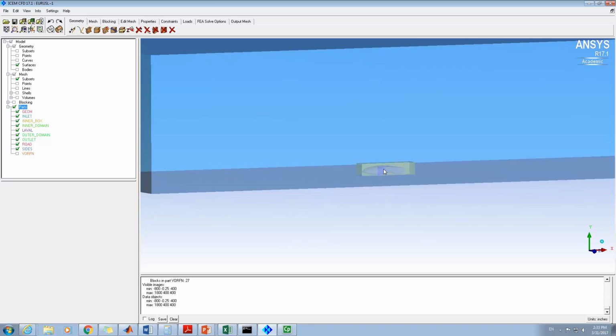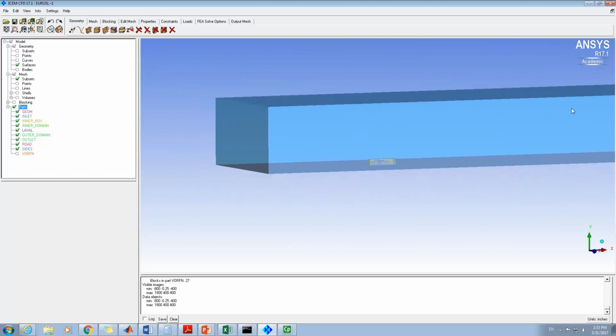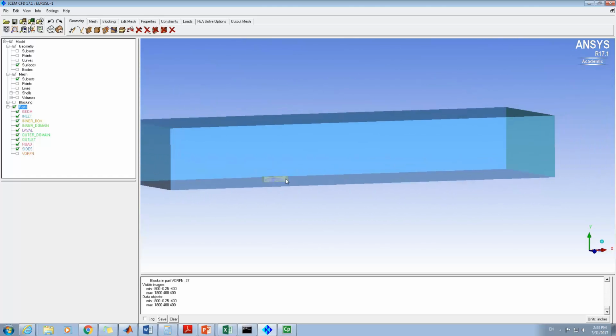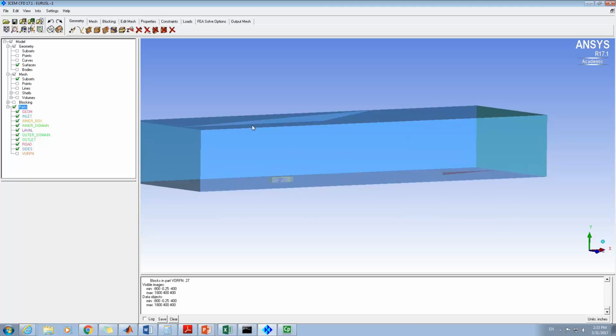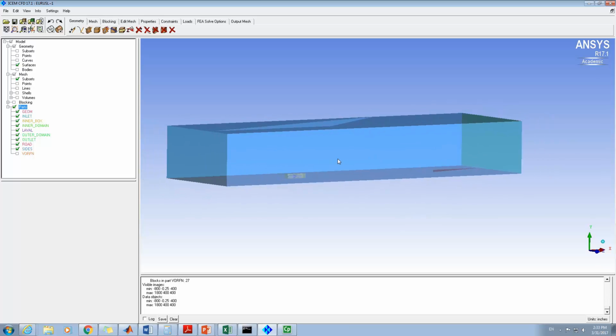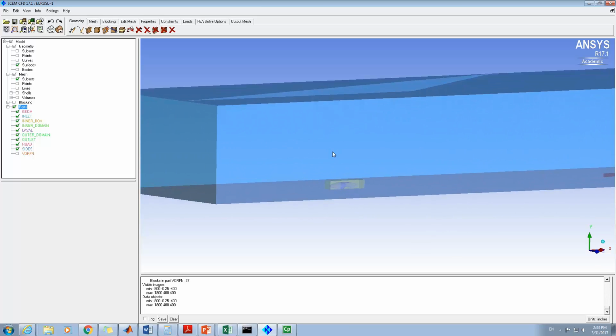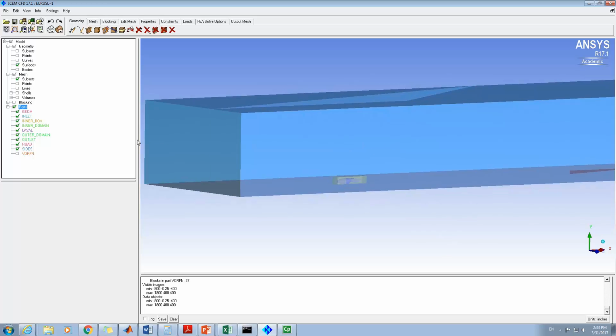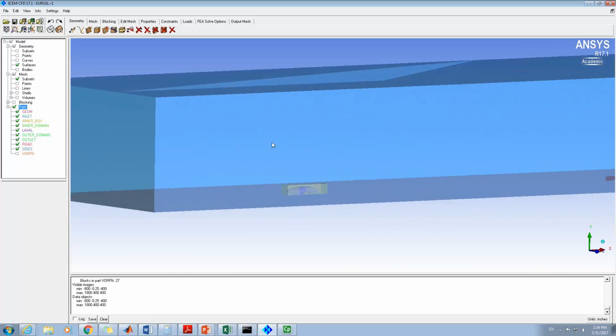However, you also do not want to use unstructured mesh for this whole space, because away from this car surface, the geometry is very simple, right? It's a very regular rectangular shape. Anyways, it's very structured geometry. So here you may want to use the hybrid mesh.